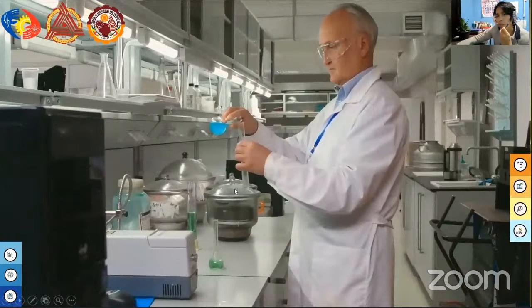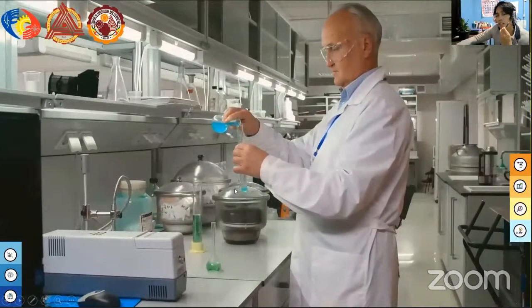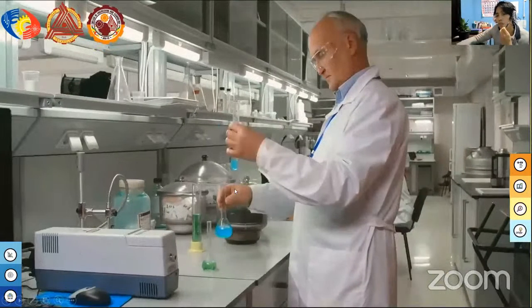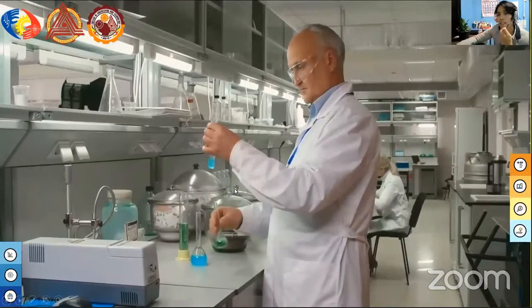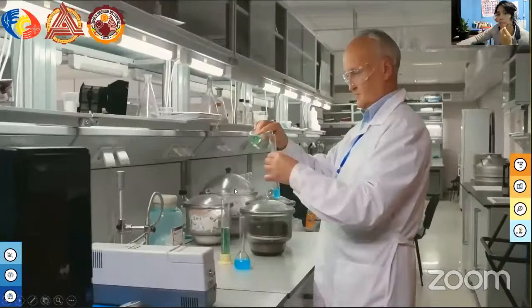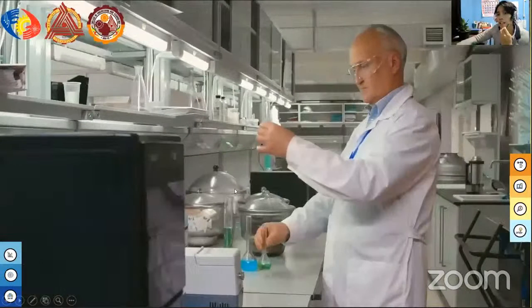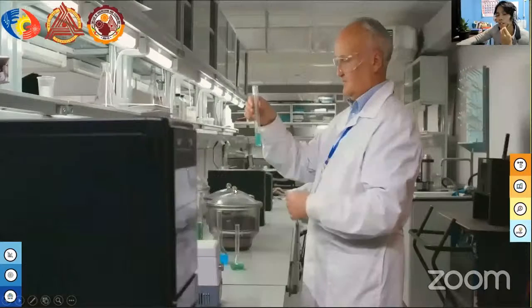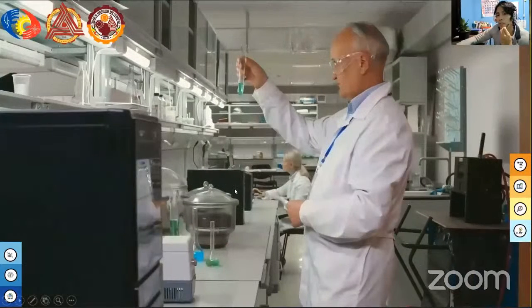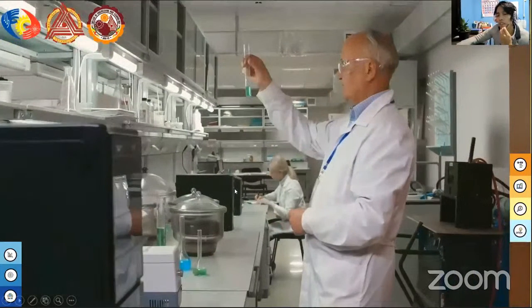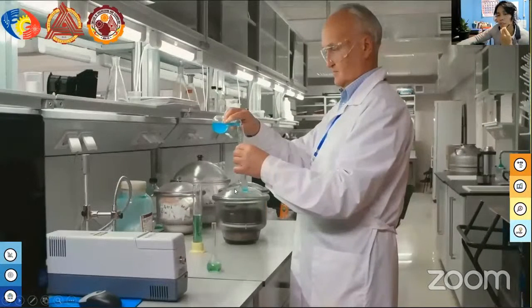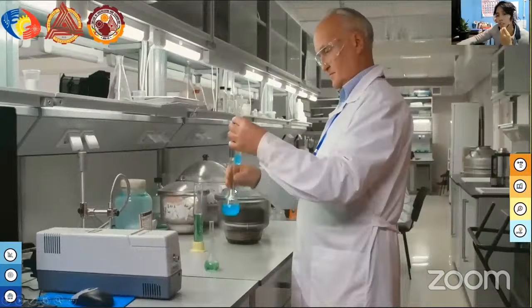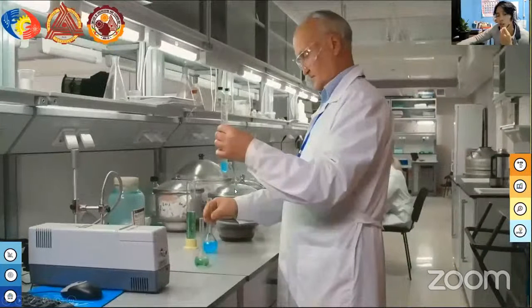Moving on to the methodology, the nanoparticles investigated in the study were produced by SAT Nanotechnology Material Company Limited. Tungsten carbide nanoparticles were 99.95% pure. Cobalt oxide nanoparticles were less than 40 nanometers at 99.5% purity. Nanofluids were prepared via the two-step method with 0.5% to 2% volume concentration in increments of 0.5%.